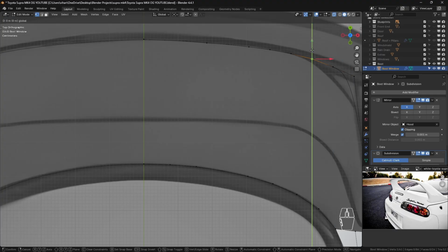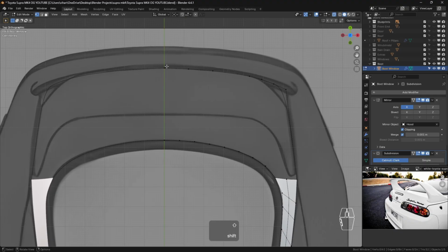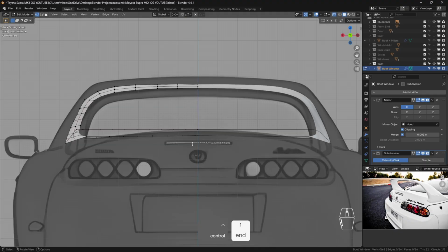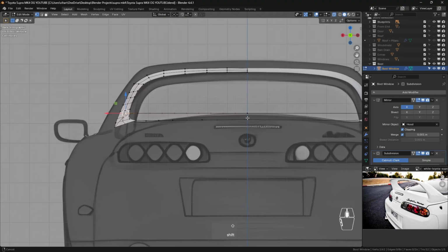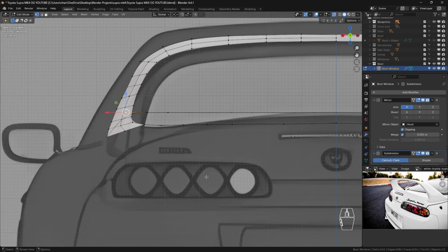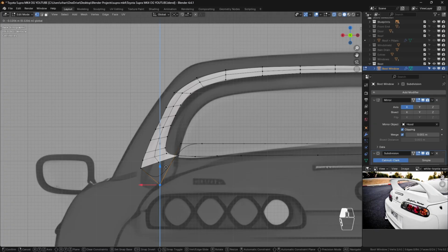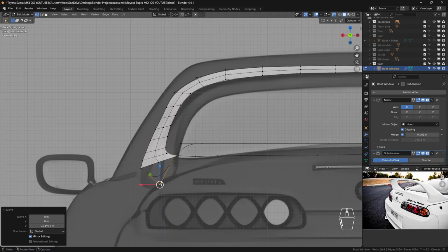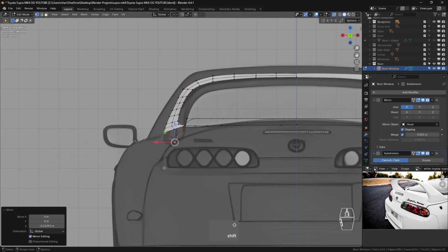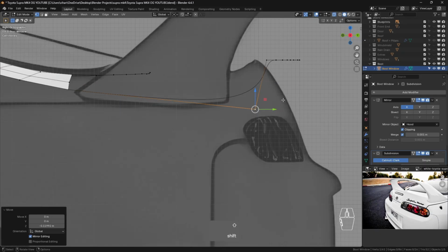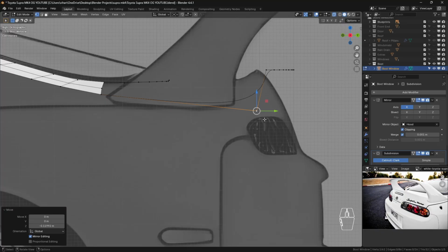Right, so once you're done aligning these, we're going to the back view right here. So this is our edge right here. When you see here, if you look at the vertex right here, if I take it to the edge right here, it's going to be only a little distance above our headlights and the curve that we have, the panel that we have around here. So we're going to go to side view and just check if this is the same distance from the panel, okay?